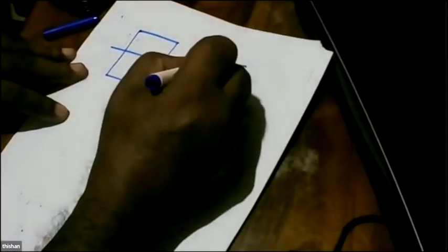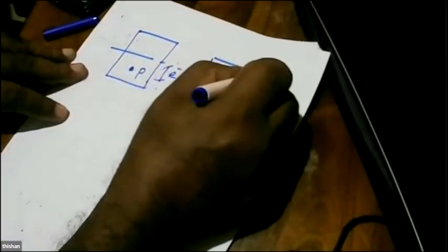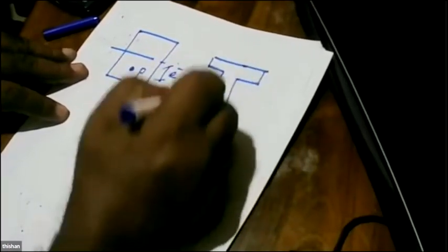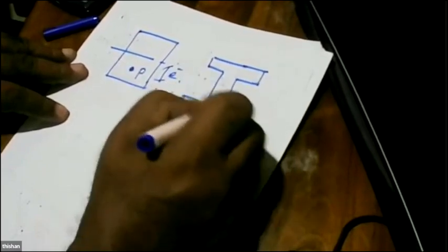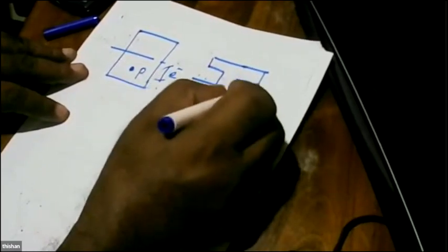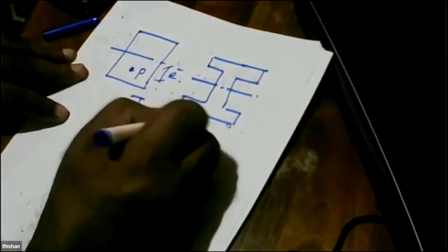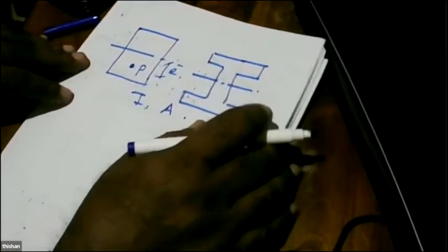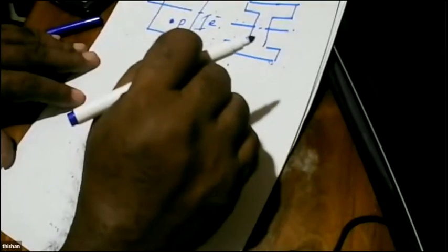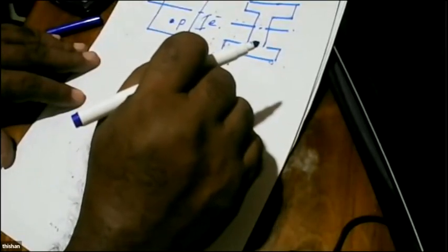So we say subjected to force P, eccentricity e. The shape doesn't matter because we are going to talk in terms of section properties, which will be I and area, where I is the second moment of area. So we are not going to worry too much about the shape, because we are going to make use of the properties.